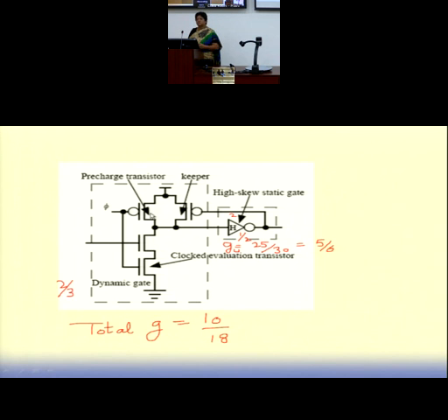I may be putting the value over here. It need not be 2:1. I need not make it the same drive capability as that of the pull down. That is not required. I can make it lesser. I can make my pre-charge unfavorable transition so that the down transition is favored. In doing so, I would be increasing my pre-charge delay. Yes. But remember, in a pre-charge block, there is only a single PMOS.